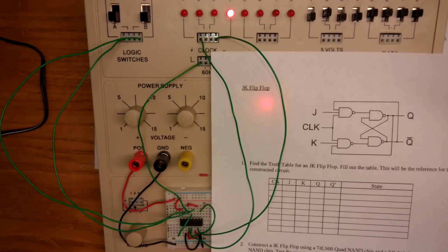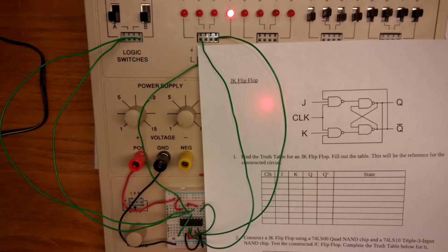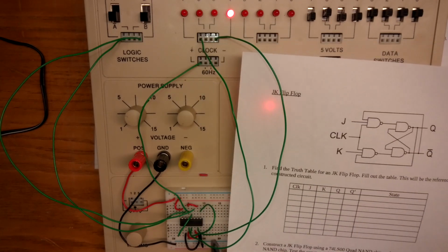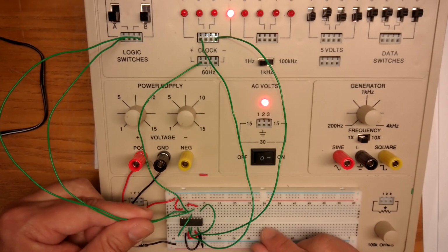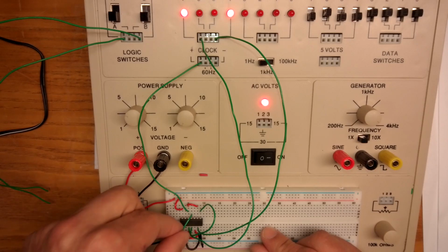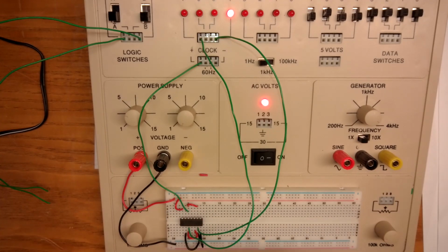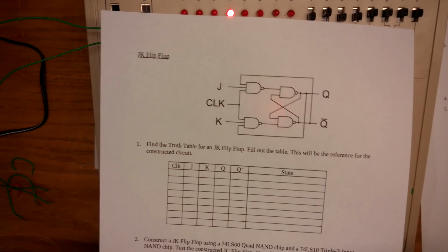Now, the problem is I need 3 input flip-flops, so you need to get a 74LS10 that has 3 triple 3-input NAND gates and use it. So you'll put alongside here, get power. You'll disconnect what's going on in the top, and you'll run these over to that other flip-flop. So I'll keep my power here, but my feedback will come off the other chip. So what I want you to do next is go through and just use those 2 together and build this.